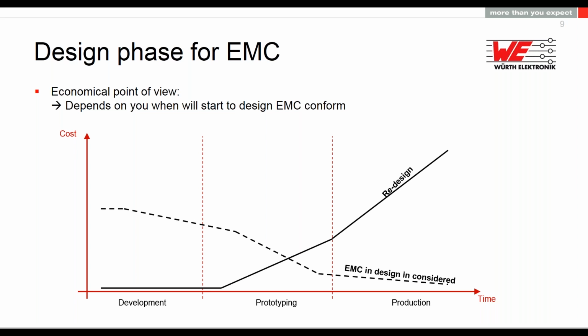Put a 0 ohm pad resistor, and if you have a first working prototype, go with your first working prototype to the EMC lab. Maybe you don't need to make the whole EMC test, but make a quick scan to see which frequencies are making a little bit of trouble and are too high and could cause trouble for the EMC final qualification.